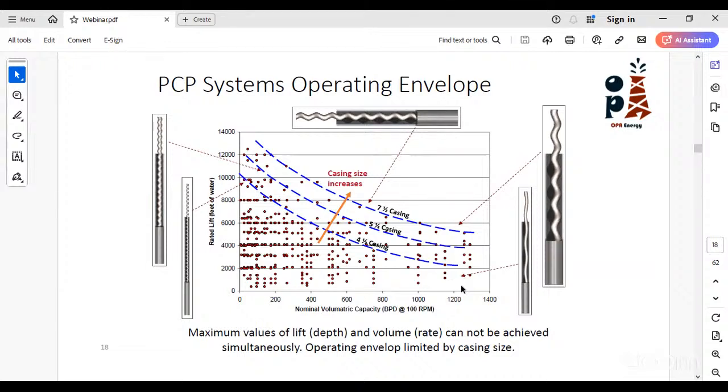Because something we will have later in the course will explain the relationship between the flow rate and differential pressure in terms of something called slippage. The slippage that we will talk about later represents the percentage of the flow rate that cannot be delivered from chamber to chamber because of the high differential pressure.